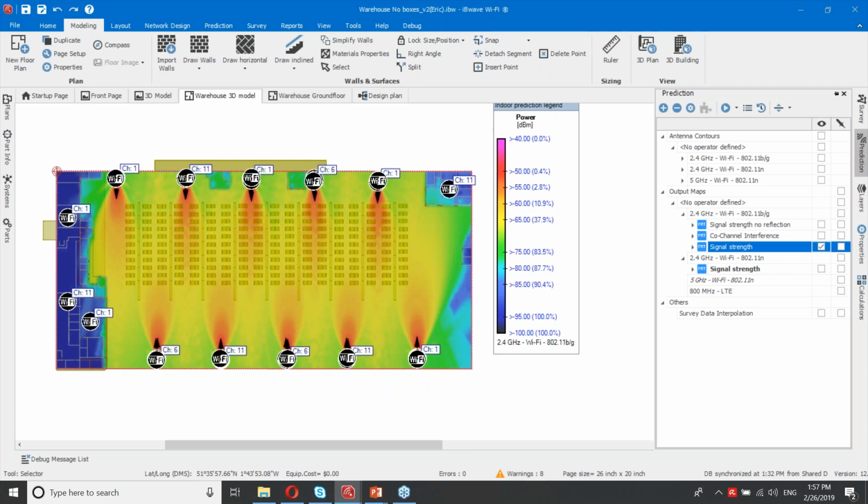You do not need to go and do that in this example along every area in a warehouse, just in between a couple of shelves. But the survey being done at Wi-Fi frequencies, it's usually done by using a spectrum analyzer to account for noises that exist, and it is always a good idea.